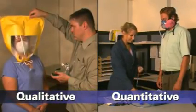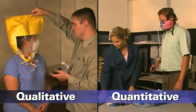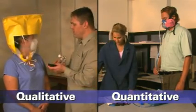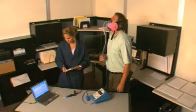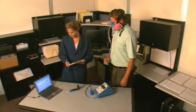So what is a fit test? A fit test is designed to test the face piece to face seal of the respirator. It can be either qualitative or quantitative and uses a test agent or instrument to verify the respirator's fit. This process typically requires 15 to 20 minutes to complete. Your respirator must be fit tested before you use it in the workplace and must be retested at least annually to ensure a continued good fit.